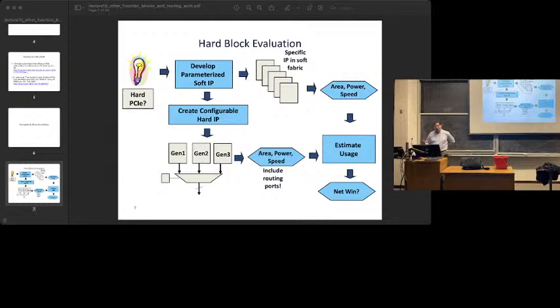We don't usually use those cutoff transistors in the programmable fabric because they do have a speed impact, right? When I put an extra transistor like this in my path to power, and I put all my logic down here, there is some delta V across this, which means all the rest of my transistors are operating at somewhat reduced voltage, which makes them somewhat slower. But for a hard block, that's not as bad. Hard blocks we can make pretty fast already compared to this programmable fabric. If they're 10 or 15% slower than they could have been, but they're still 3 times faster than the programmable fabric, you say that's pretty good.